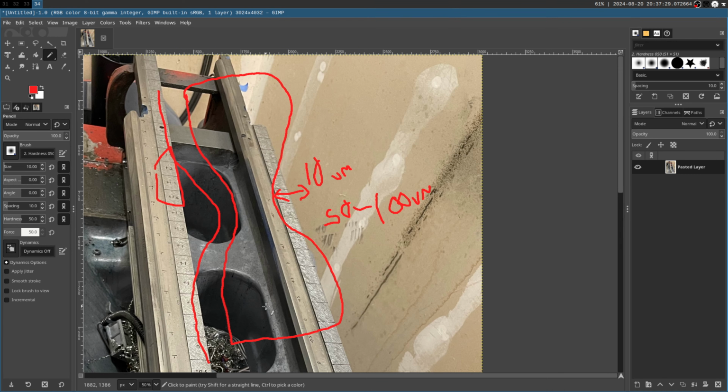However, I find it convenient for a reference because it's easier to set up gauges and indicators and measure things. Also, the surfaces that don't contact things give you a historical reference point as to what was flat. Maybe the next owner might not know that, but I know that if I restore this machine in 10 years, I did this in the past.